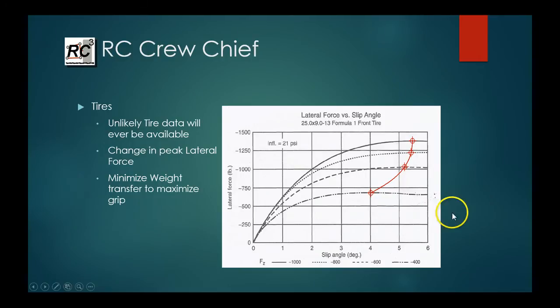And you can see here the range for this tire's operating range is from 0 to 6. Once you get beyond 6, then the lateral grip starts to fall off. So what we can gather from this graph is we got lateral grip, slip angle, and then each one of these lines here is a line of constant vertical load. So the bottom one, that's the performance with a 400-pound vertical load. That's 600 pounds, 800 pounds, 1,000 pounds.